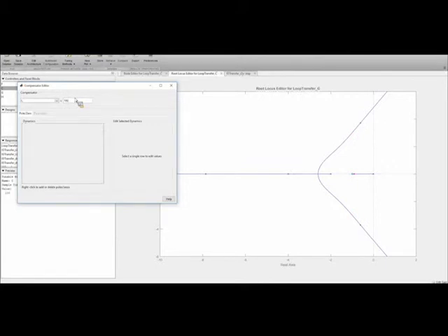So Ben, getting back to your question, you said that we have to increase the gain to infinity to have a perfect pole zero cancellation. And you said that if I increase the gain too much, these poles are going to move into the right-hand plane. You're exactly correct. But you can see even for gains where the closed loop poles have not gone into the right-hand plane, you still get an approximate pole zero cancellation here.